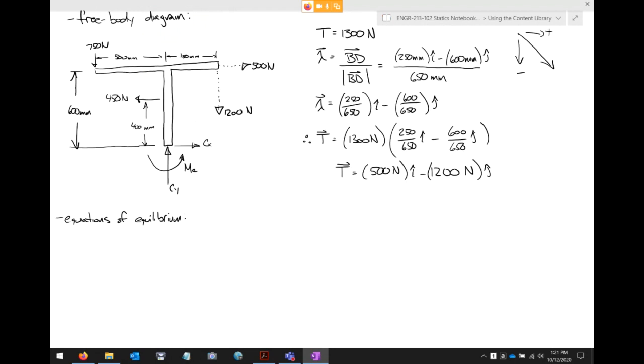That's one of the things that you will find a lot of times when you're dealing with problems with fixed supports. What we did on Monday, we were dealing with hinge, roller, simple supports. Sometimes you've got to be strategic. Like if I sum moments at A, that eliminates two of my unknowns, and then I can solve for the reaction at B or something like that. A lot of times with fixed supports, it's even easier. It really doesn't matter what order you go in because all the reactions are at the same place anyways. So let's just do it one at a time.